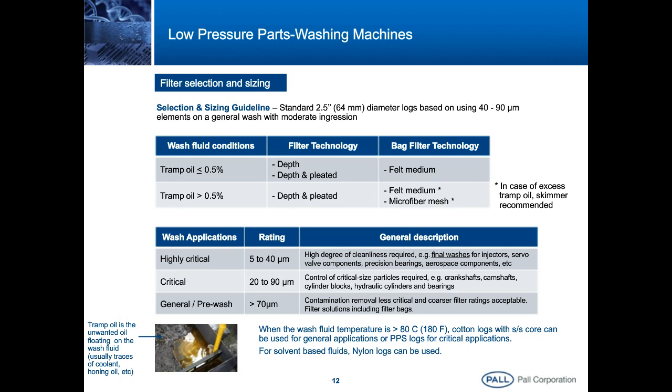Filter ratings are related to the applications themselves. If the application is highly critical, consider components like injectors, servo valves, or precision bearings. You will select a filter rating between 5 to 40 micron.